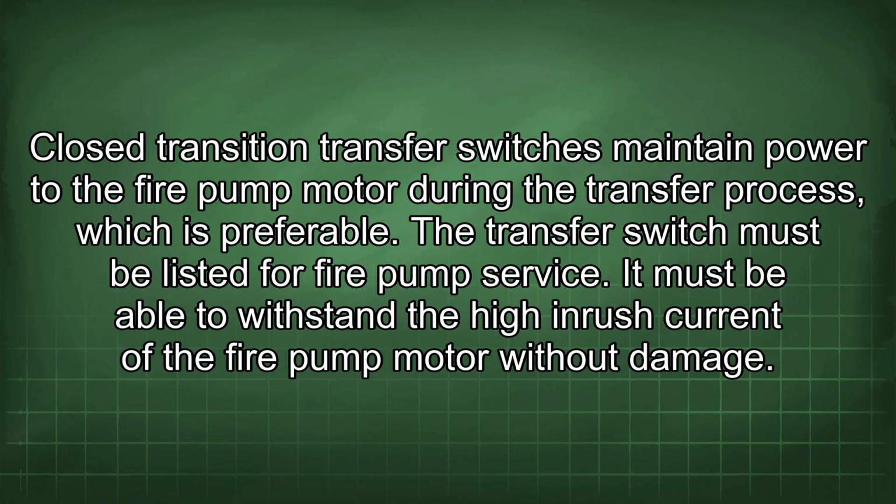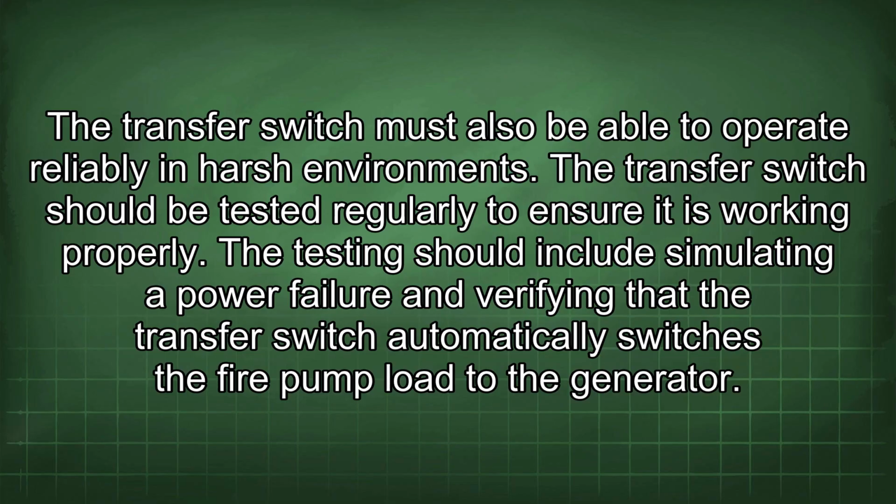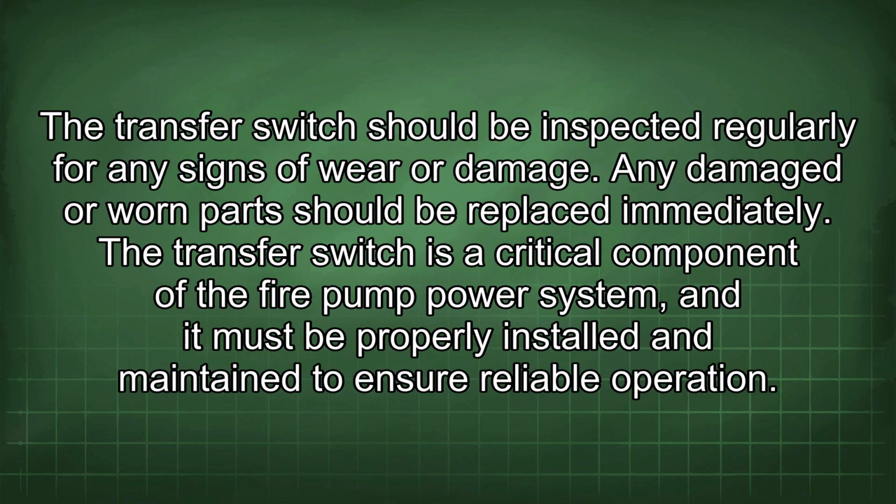The transfer switch must be listed for fire pump service. It must be able to withstand the high inrush current of the fire pump motor without damage. The transfer switch must also be able to operate reliably in harsh environments. The transfer switch should be tested regularly to ensure it is working properly. The testing should include simulating a power failure and verifying that the transfer switch automatically switches the fire pump load to the generator. The transfer switch should be inspected regularly for any signs of wear or damage. Any damaged or worn parts should be replaced immediately.